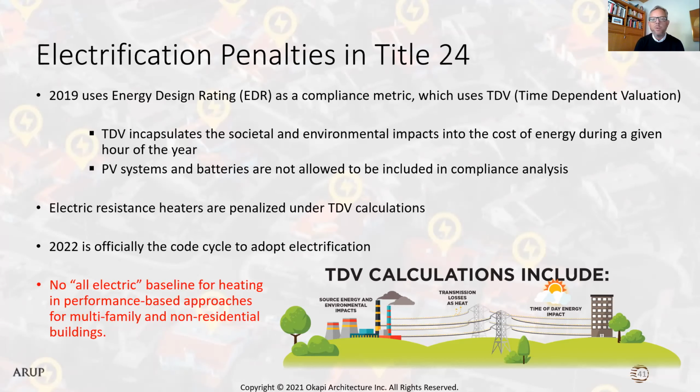You might even work with a local authority having jurisdiction or plan review that isn't quite sure how to review the documentation for, say, your energy compliance. And so, in CALGreen and showing compliance with energy performance, it's based on time-dependent valuation, which tends to privilege, say for heating at least, a natural gas-based system. And so you end up with an electric building that is being compared against a natural gas baseline, and you can show a penalty for that.